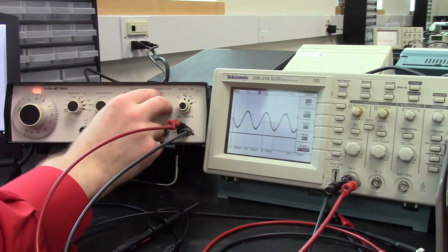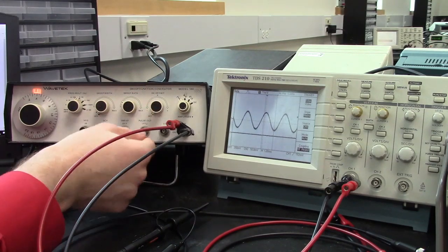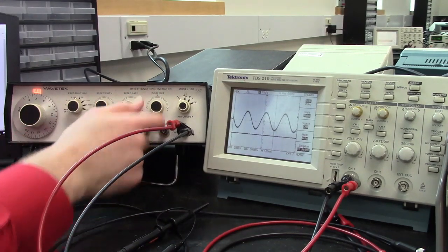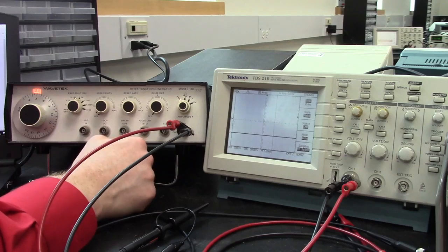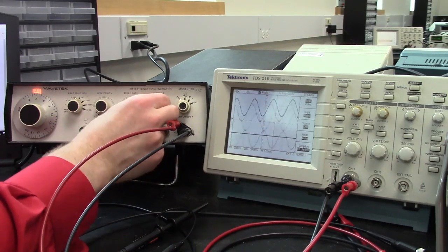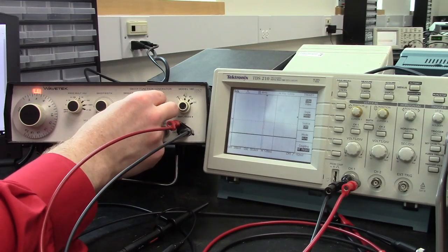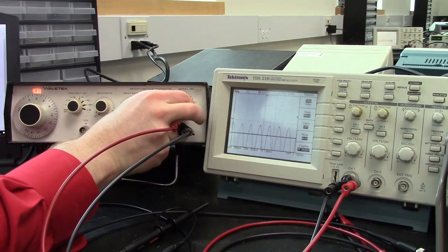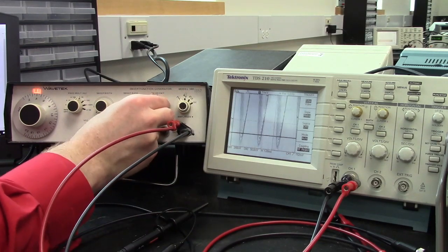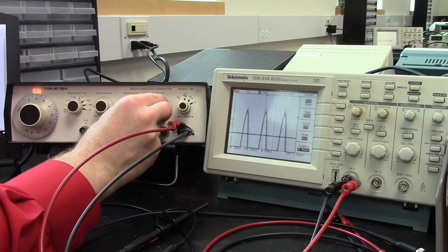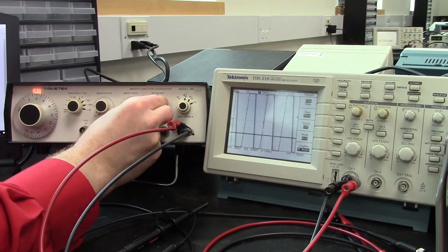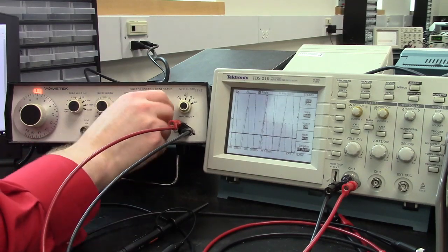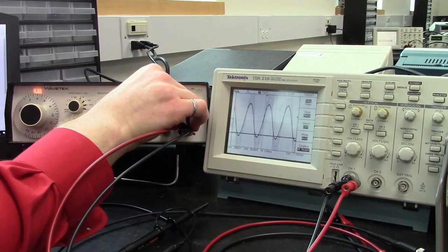Another thing it can do is set a DC offset, and that's with this knob here. So again, all the way to the left will turn that off. If you turn that on, then we've got a signal which is moving up and down here. So increasing the amplitude will allow that to still trigger and see what's going on. So we're shifting the signal up and down with this offset. We don't need that, so we'll just turn it all the way to 0 and then turn the amplitude back down.